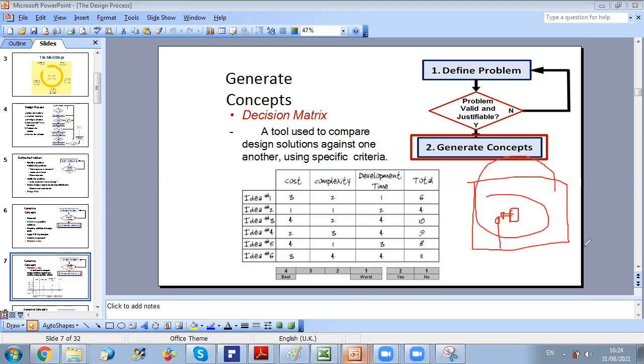And also you are trying to, if you want to have very good indoor air quality, you need to increase a lot the proportion of fresh air entering. And you know that fresh air, the higher the proportion of fresh air is, then the cost will increase because when you recirculate air, the cost of cooling is lower than the cost of cooling air that's coming from outside.